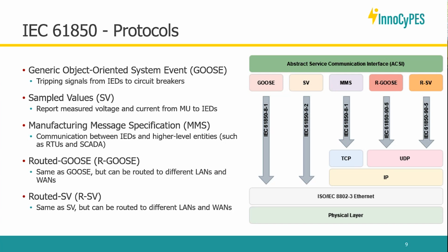In IT, we can change the equipment every 5 years. There is no problem. Instead, in the OT environment we cannot do that, because it would mean stopping operations. Also, the cost of OT equipment is usually higher, so it's not easy to update those systems. Then adding things like a key distribution center or a side channel increases the complexity of the network. Network architects who work in OT infrastructure try to keep it as simple as possible, because the fewer components, systems and services you have in the OT environment, the less likely it is that something fails. So just keep it as simple as possible.